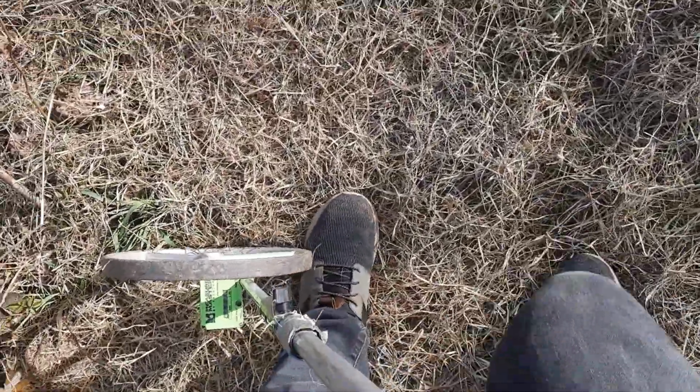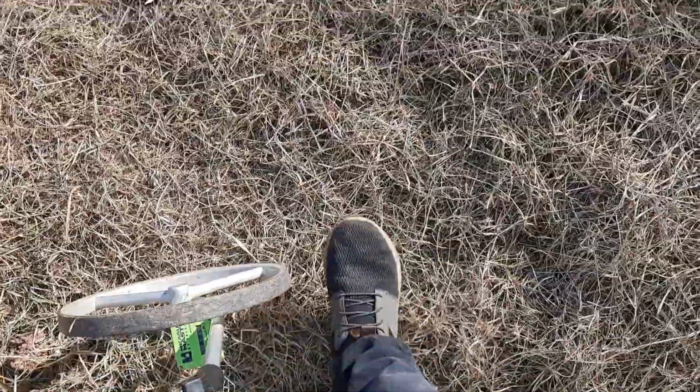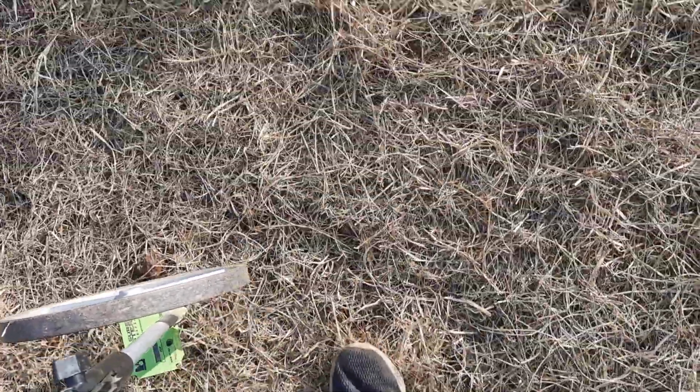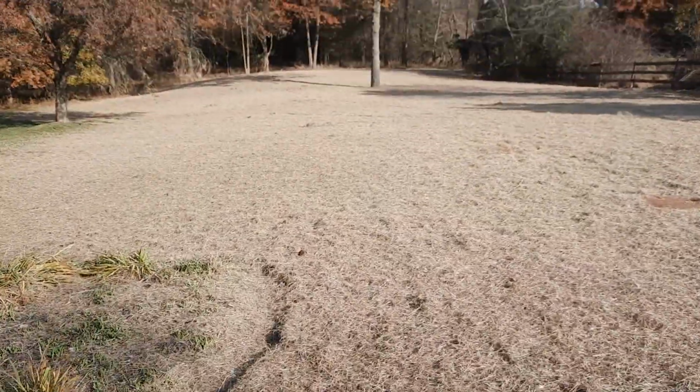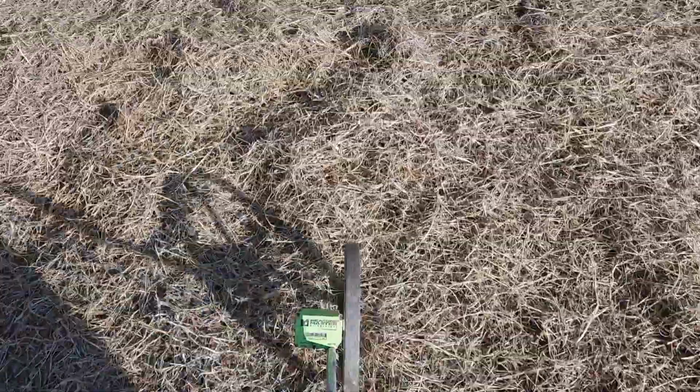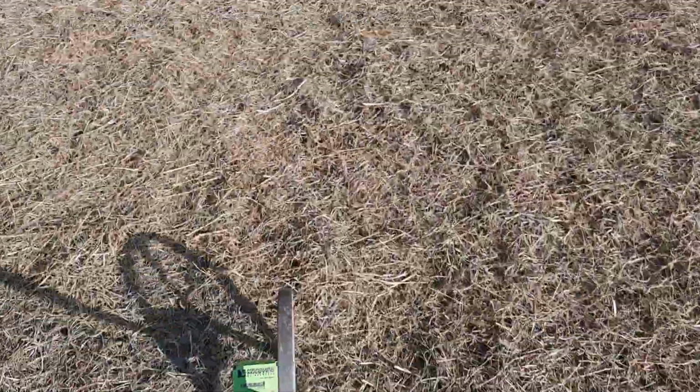And then from here, I'll take my steps and I'll go 1, 2, 3, 4, 5, 6. Boom, put it down. Oh wow, there's no landscaping features here. Good. Continue. Once you pass the obstruction, we go another 1, 2, 3, 4, 5, 6, and we're back on line, and you continue your measurement.